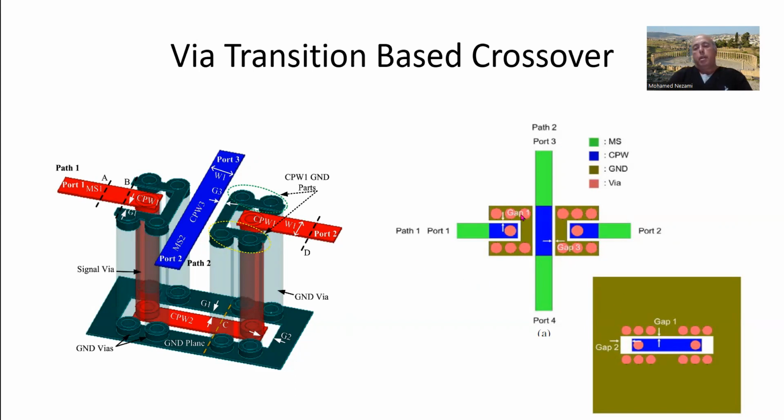Same way they can be done like this, and usually we design it, and the challenge is to design a few ground vias, okay, that interconnect the ground on the second layer that you're jumping to, and mimic, in that case, your job is to make it mimic as if it's really a connector type.